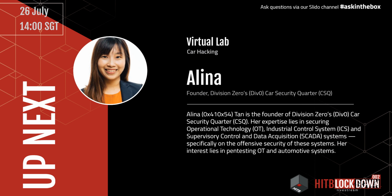How the ECUs identify each other is through the specific identifier number, the CAN ID. For example, if you played the CTF yesterday, you have different IDs running through, right? So there's no authentication involved. How the ECU knows that the traffic is for them is through the data bytes and the ID. So there's no authentication in there except for UDS.